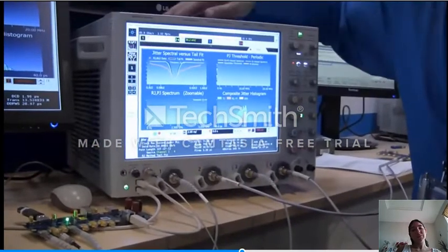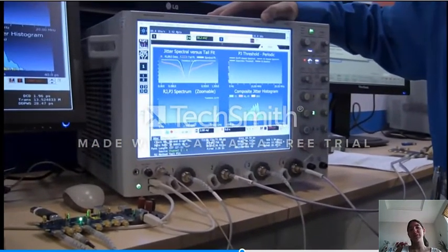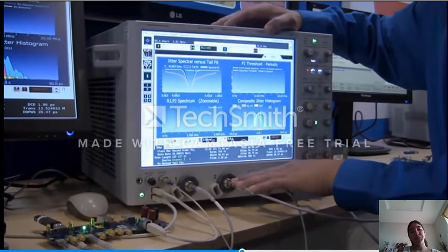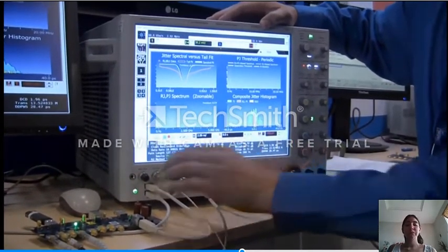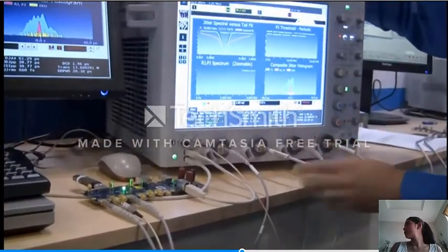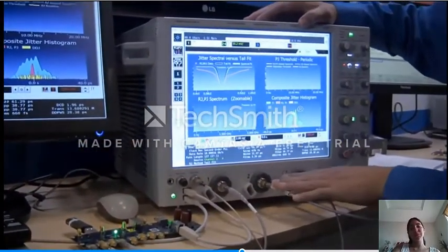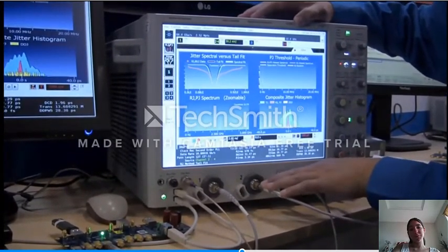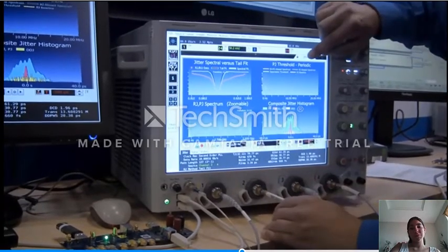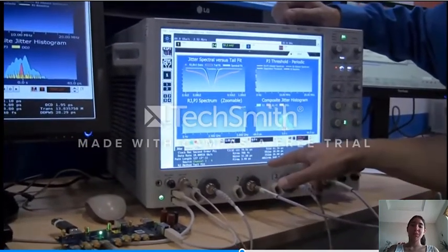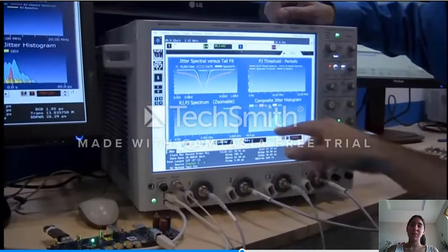So here I have a 33 gigahertz oscilloscope, and I'm measuring a 5 and a 10 gig SuperSpeed transmitter signal integrity. So channels 1 and 3 are connected to a simple USB 3 flash drive running at 5 gigabits per second. Channels 2 and 4 come off our high performance bit error rate tester generating a 10 gigabit per second signal. So these are data inputs. USB 3 in through here, 10 gigabit per second USB 3.1 like signal going in here.